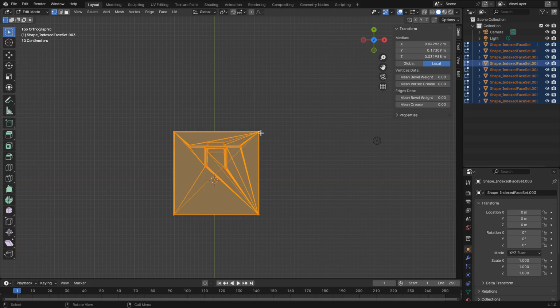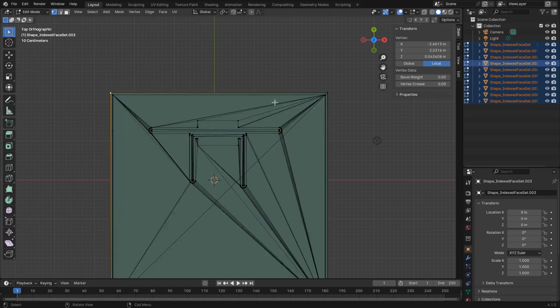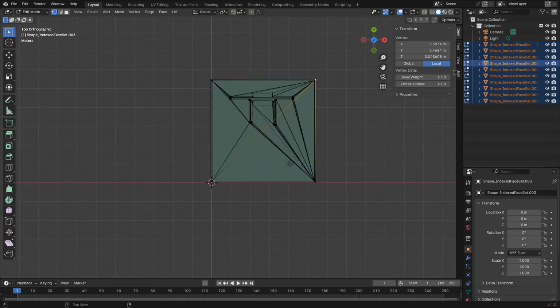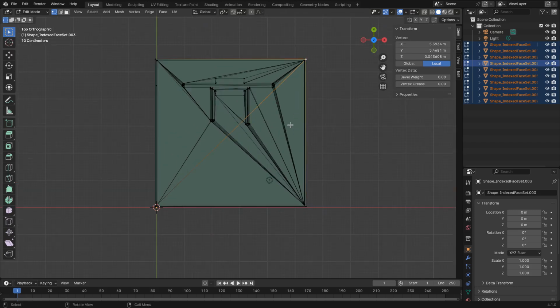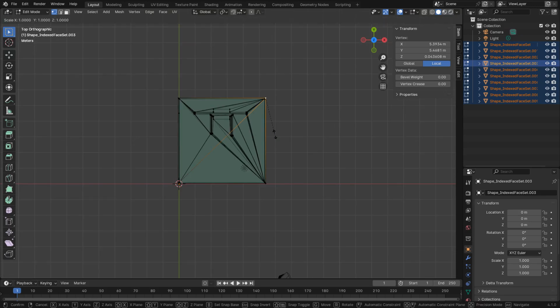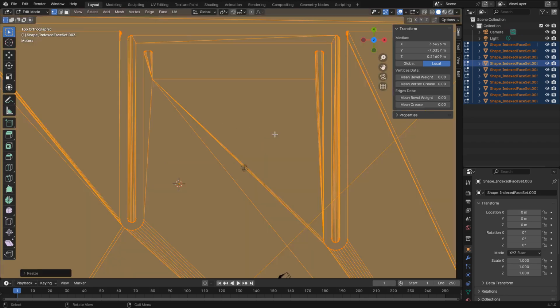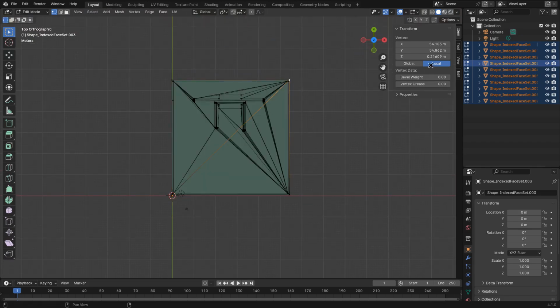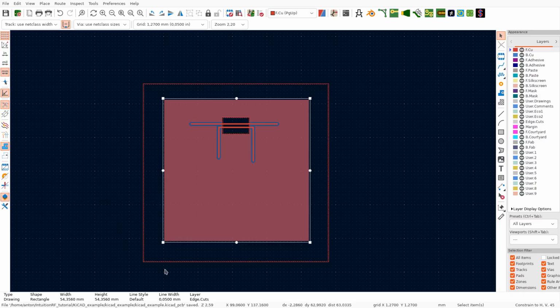Okay. And now we should have a, so that's our PCB size here. It still is not correct because we want to have it 10 times bigger. Like this. And now we have a PCB size of 54 by 54 millimeters, just as in KiCad. If we do something like this, yeah, 54 by 54 millimeters.